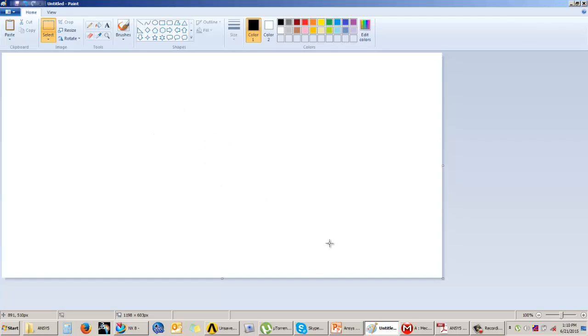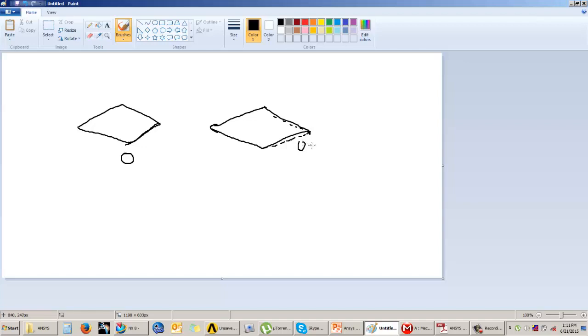So suppose we have a quad element. Let us say this is perfectly lying inside the plane and there is no deviation, so the warping factor is 0. But in the same case, let us say this is the element, and from here we have some deviations, so here you will have some deviation, let us say 0.1.